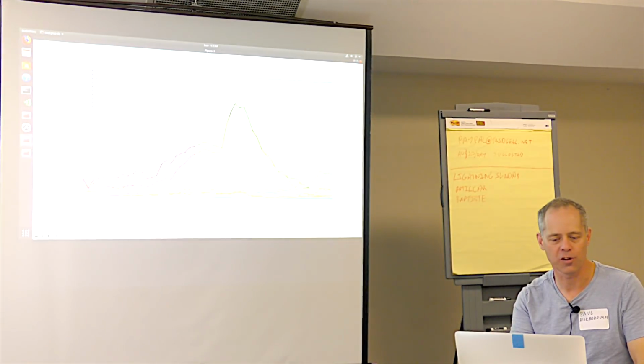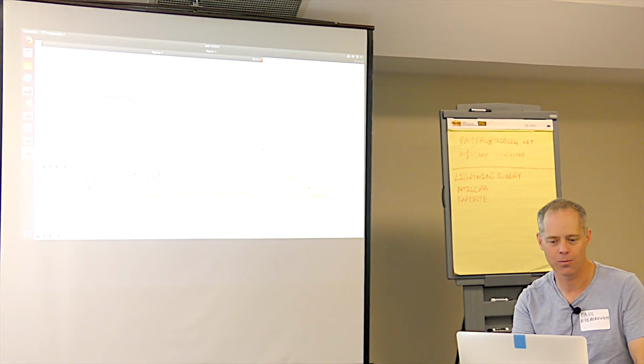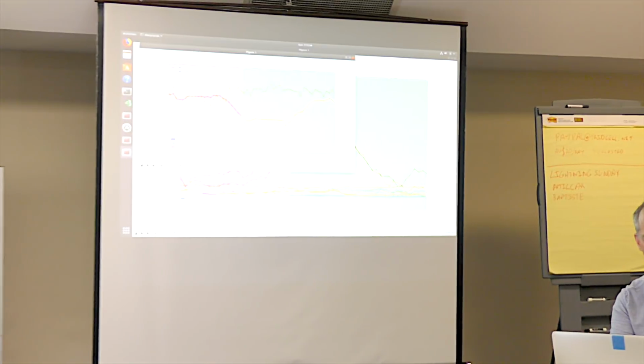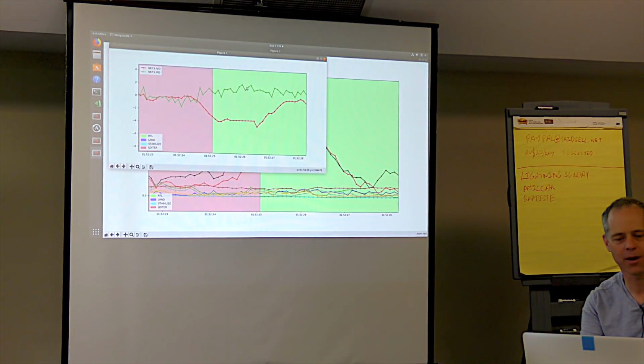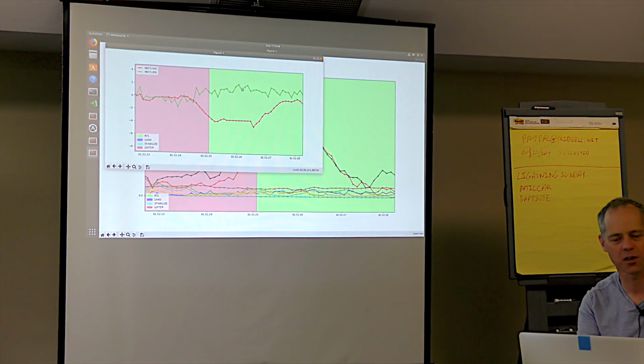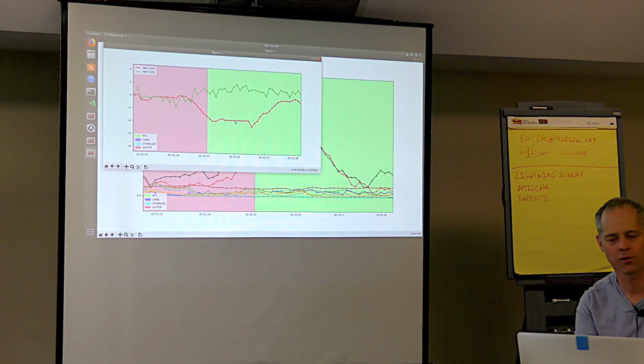So now we can have a look at some of these other graphs and go, what's happening here? Well, at this point in time, we've got the baro innovation. Baro innovations aren't great, they go up, but you can see once again that the vertical GPS innovation jumps. So in this instance, this looks like we've got an issue with a GPS that is actually glitching.